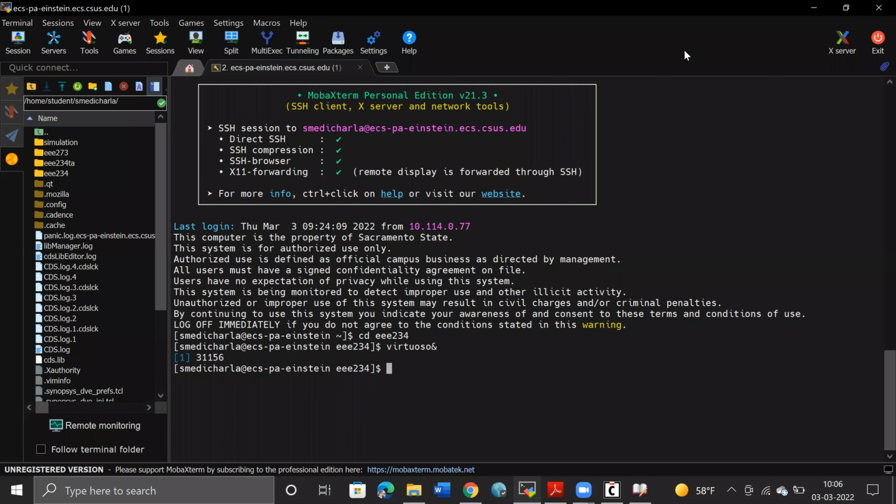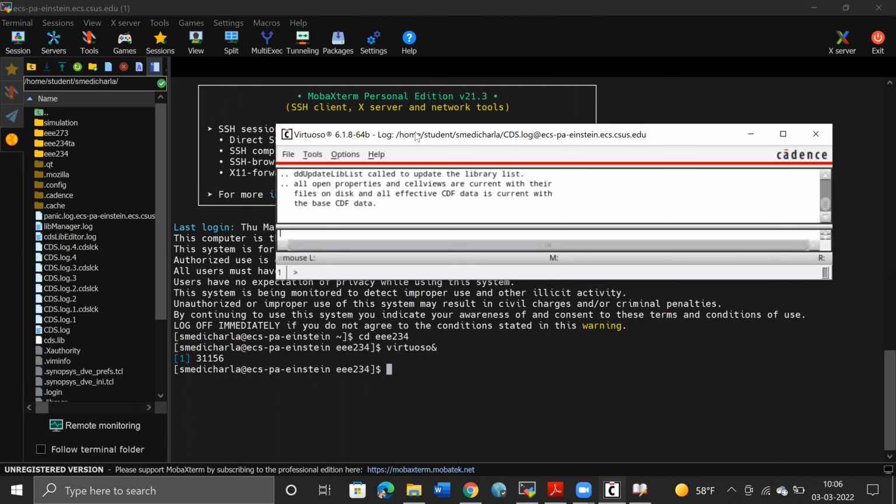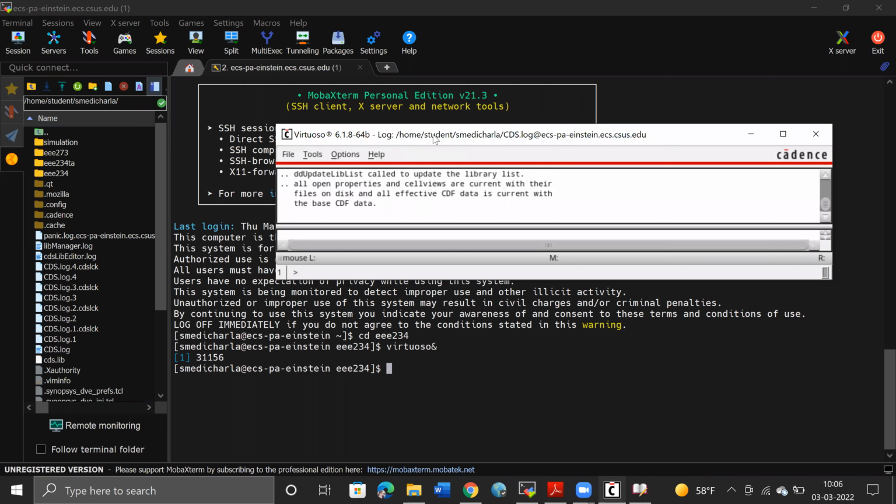You are now ready to design schematics on Cadence Virtuoso EDA tool. Now, this is the command interpreter window that we've opened in the previous video. Every time you invoke Cadence Virtuoso, it is best to exit it entirely before logging off the server. This is going to make sure that there are no locks on your files, that you make them inaccessible for edit the next time you open Virtuoso.